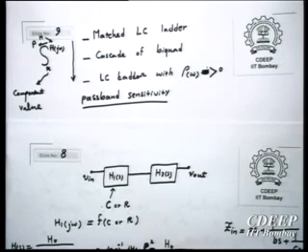The reason is, specifically in the case of a ladder filter, because rho suddenly increases, we will have a jump in the sensitivity. In the case of biquads, if the biquads have a high Q, again that will be a problem, because as soon as we reach the transition band, there is a rapid and very high sensitivity to component value, because Q of the pole is very large.